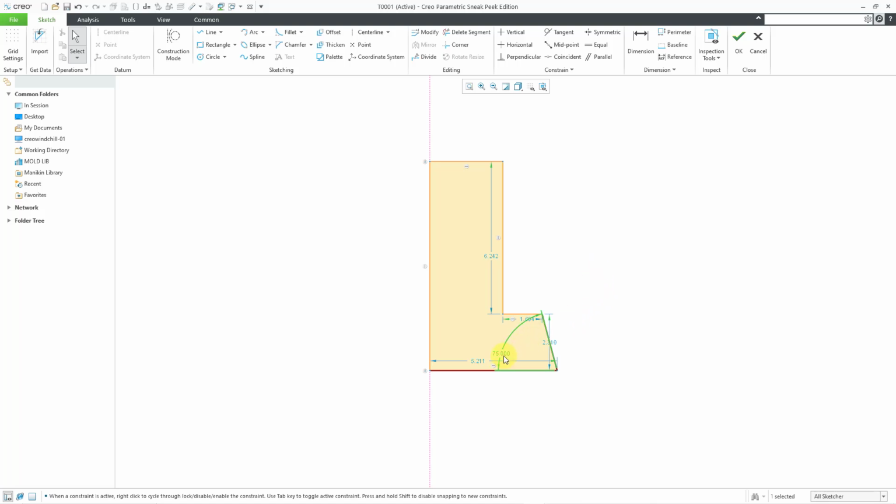And let's see, for the other different dimensions, these are way out of whack for what I want to use. I actually like this dimension and this dimension, but I want to throw in a couple of diameter dimensions. So let's go to the dimension command, and I will do 3 alternating left mouse picks, starting either on the vertical center line or what I'm dimensioning to.